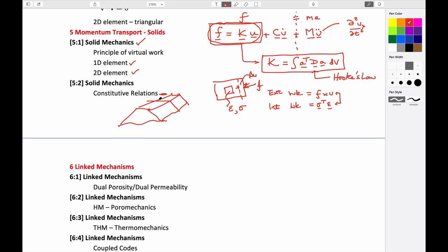If you're applying a load along the top of this structure, then that load is affecting every single one of these laminae, and they're all trying to expand laterally. And so the appropriate condition there is that the strain in that third direction, whatever we call it, Z, is equal to 0, which is the condition of plane strain.